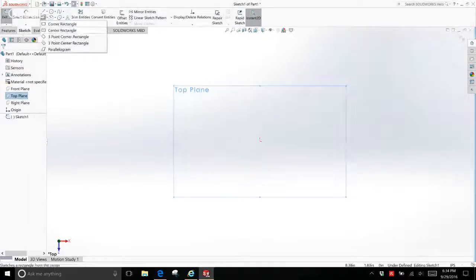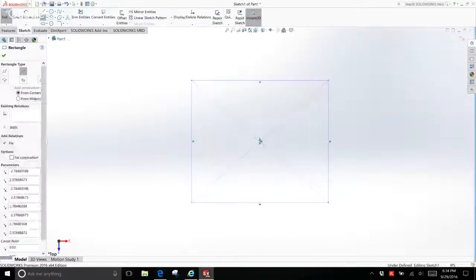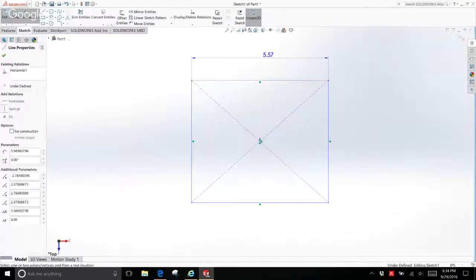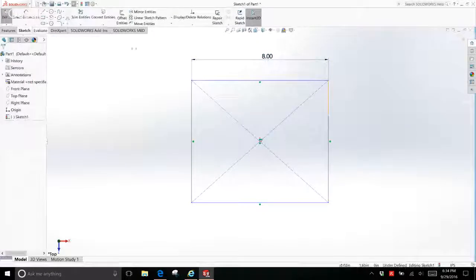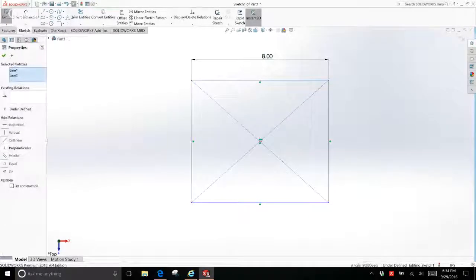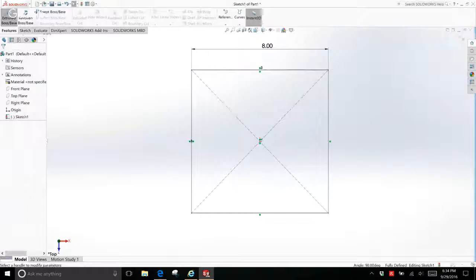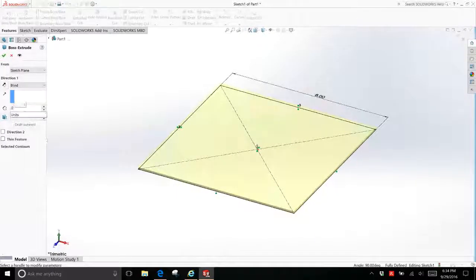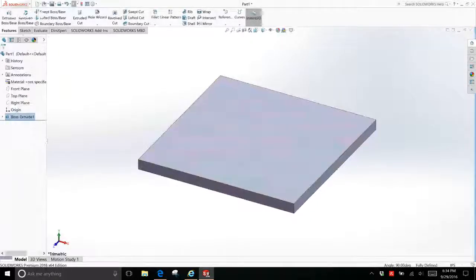So I'm kind of envisioning that this pump holder would have some kind of a base. And maybe this base might be, let's just say, 8 inches square. So I'll just make those dimensions equal. And I want the base to be maybe a 1/2 inch thick. So this will represent a 1/2 inch thick piece of metal, of steel or something.